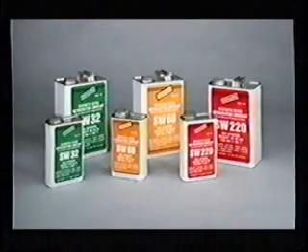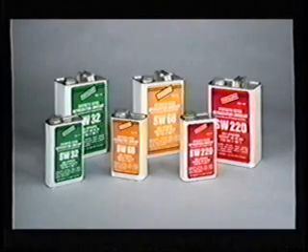The new refrigerants used with the Carlyle compressors require new types of oil. Synthetic oils compatible with the latest refrigerants are completely different than the older petroleum-based oils. The polyester oils required for the new refrigerants absorb moisture faster and in greater quantities than did the mineral oils used in the past. Care must be taken when handling these new oils to avoid contact and moisture.